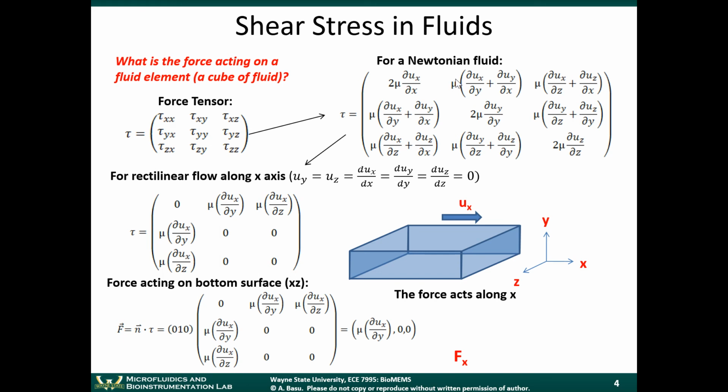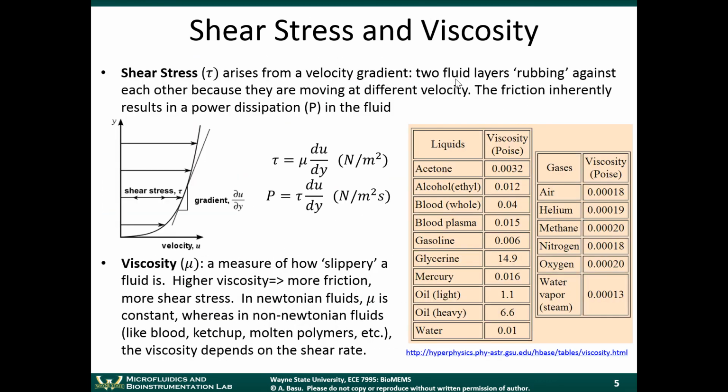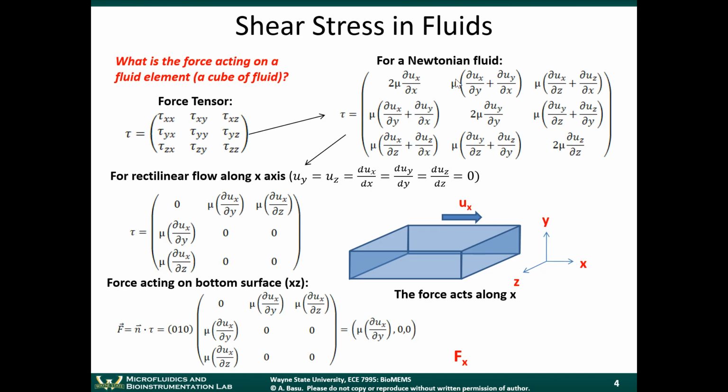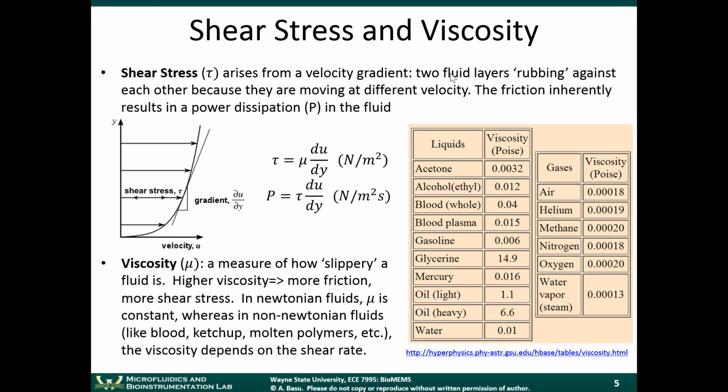Okay. Now, just the intuition behind stress. Actually, maybe let's talk about this, and we'll come back to the previous slide. Whenever fluid is moving through a channel, it creates a velocity gradient. The reason a velocity gradient is created is because at the walls of the channel, the fluid doesn't move. The velocity of the fluid is 0 at the walls of the channel.